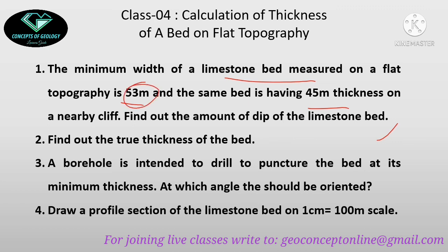So I have the W here and I have the T dash here. Try to find out the amount of dip of the limestone bed. You use the equation which is appropriate for this. The second question is to find the true thickness of the bed. Again use the equation. A borehole which is intended to drill to puncture the bed at its minimum thickness. Minimum thickness means what? The stratigraphic thickness or true thickness. At which angle should it be oriented? I will not give any hint about the question. Try to draw the profile section and find this out.